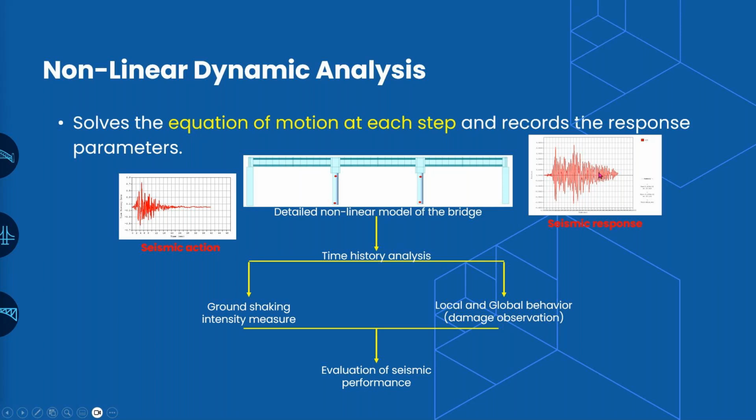Now, we should note that this peak response within the structure in terms of acceleration or displacement could be different in case of different time history records. So there is always a certain amount of variation in the response that we are getting from the structure in case of the nonlinear time history analysis. So it is very important to adhere to the recommendations of the code to consider a certain uniformity or a surety in the analysis results.